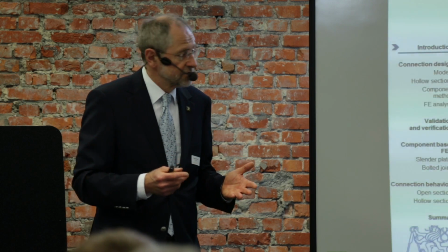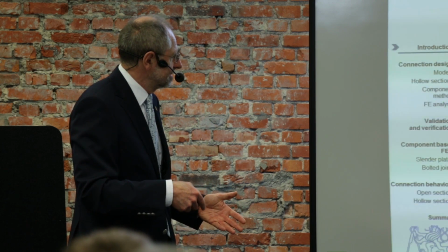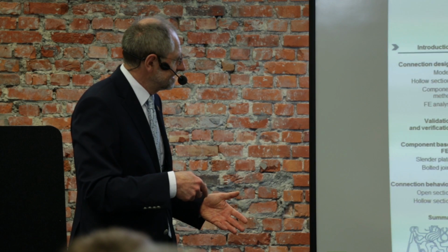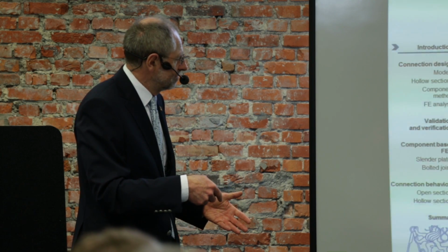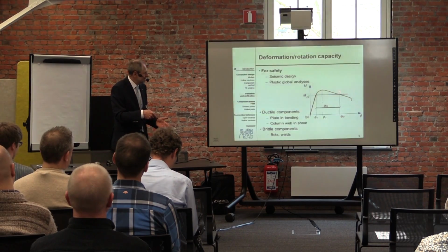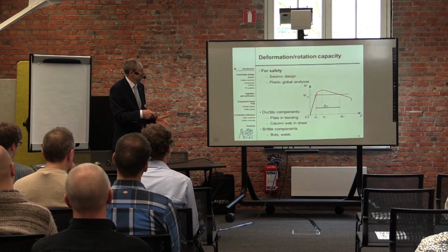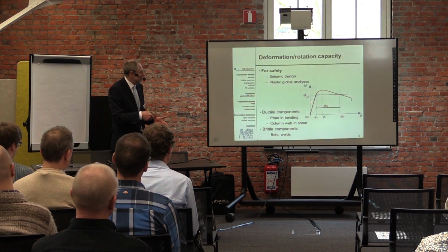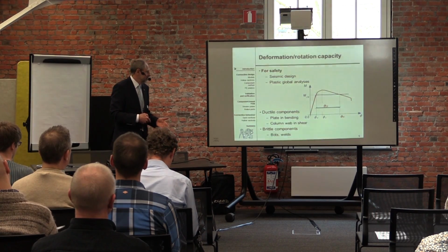And if we are going for plastic design, it's crucial. So rotation capacity is also sensitive to level of design. If we are very low, the deformation capacity may be more. And the plastic deformation capacity, it is deformation capacity. The elastic part here is a bit out of scale. The elastic part is not of importance.